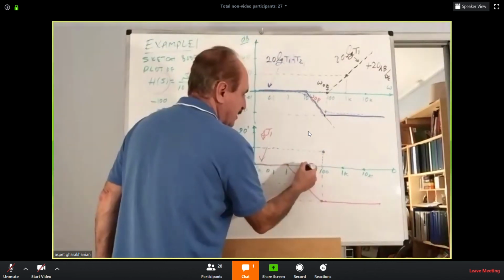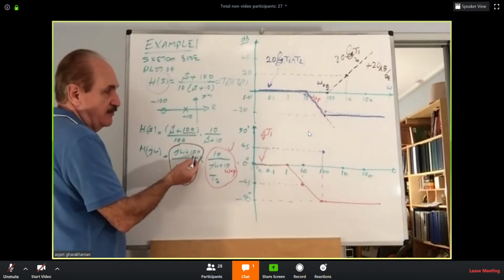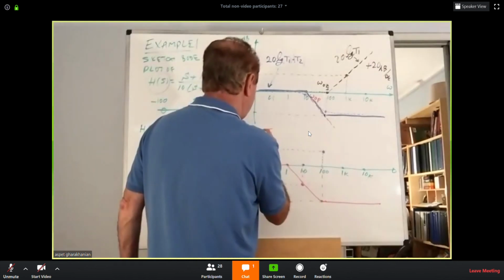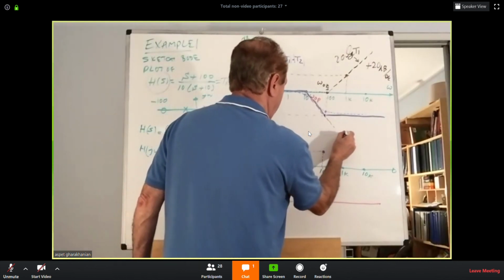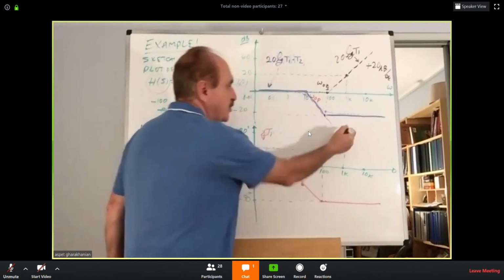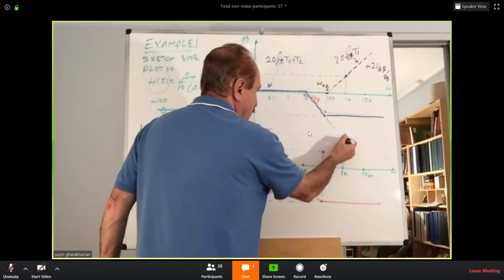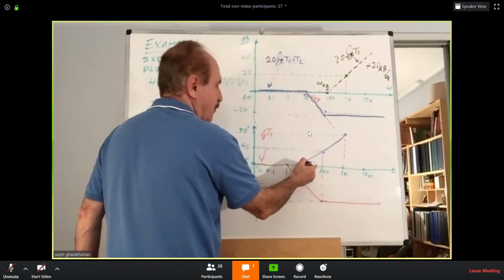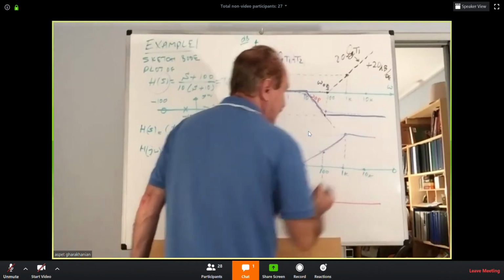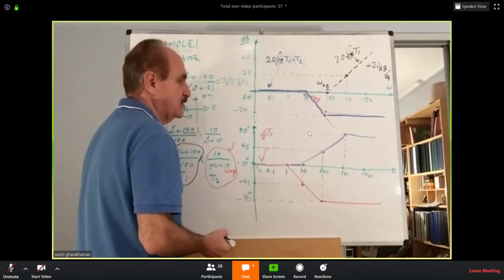So you will mark that. At a frequency 10 times over the 100, it's almost like a 90 degrees lead. So it will bring you right there. These 3 points will be automatically collinear. So you will construct them. From that point onwards, it will stay leading 90 degrees. Under the 10, it will be 0 degrees phase shift.